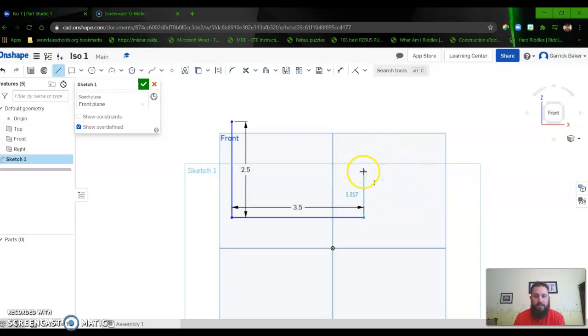And I'm going to complete this shape. So from here, I'm going to go straight up. And the height of it is 1. So I'm going to click, then type in 1, then go over. The distance of this line is 2.5. I'm going to click and type in 2.5, go straight up, and then I could click and type in the line again,